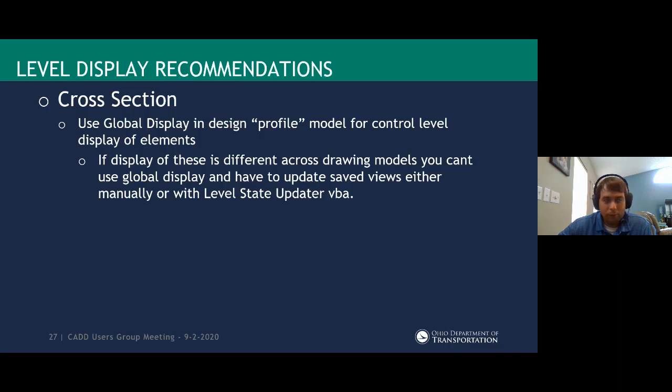But the second you need them differently, you're going to have to edit each individual saved view, and there's that VBA available. But keep in mind, if you turn it off globally, that trumps your saved view. So if you need something to be different per given one, you can't have it turned off globally, or you won't be able to turn it on for that one given one, if that makes sense.